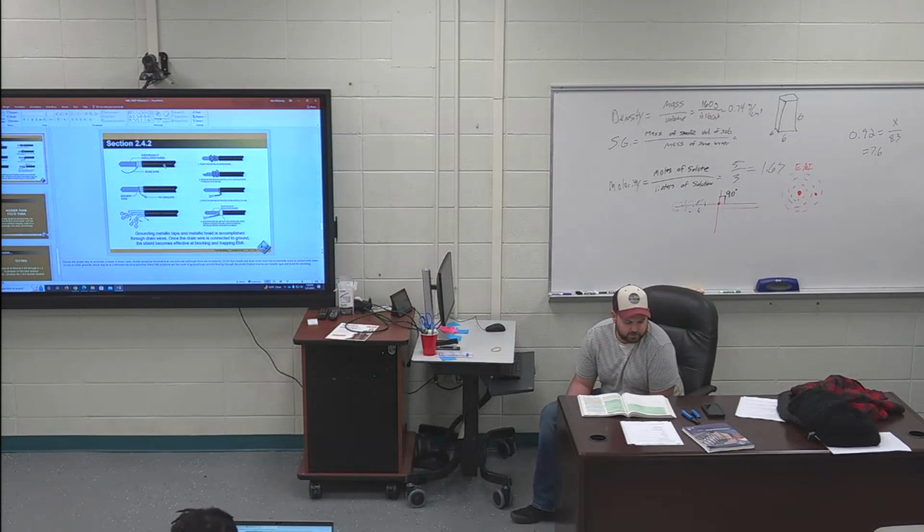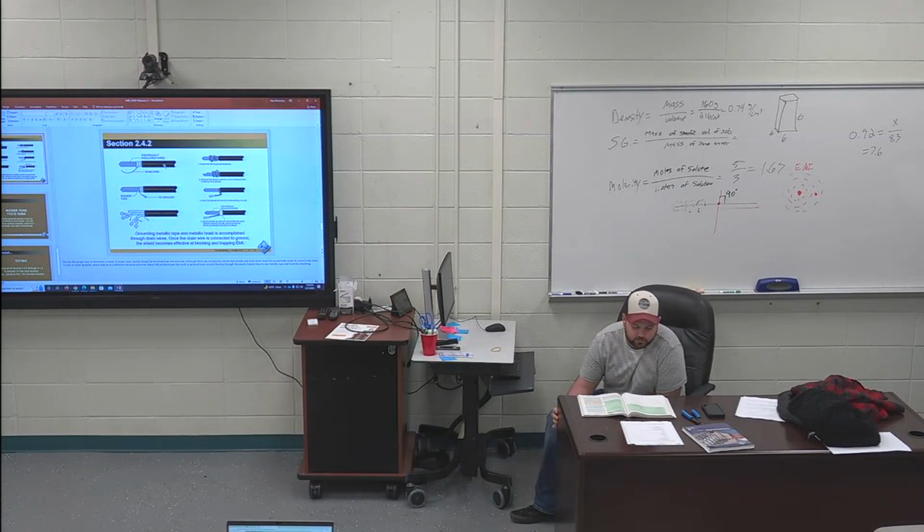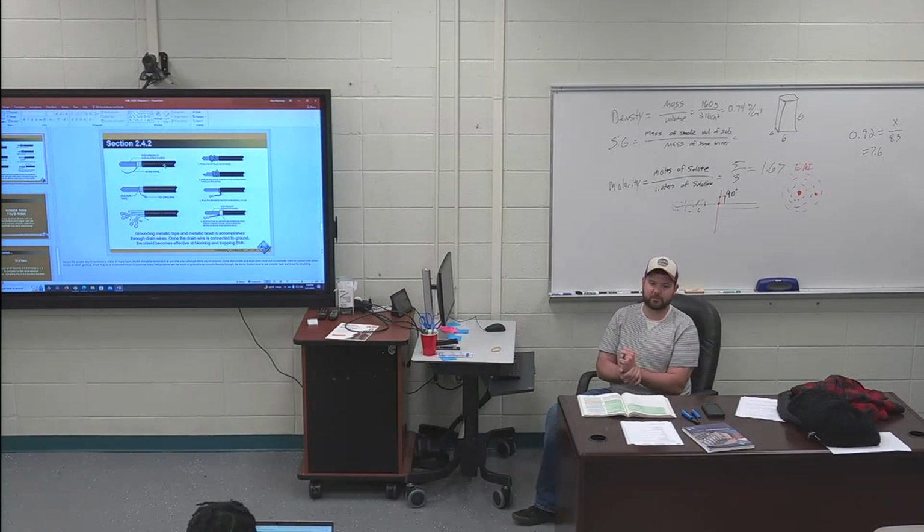Number one, wires installed in spring-loaded terminal blocks are held in place by spring contact, A. Two, coaxial cables are terminated with type F connectors, which is C. Three, a service loop should contain sufficient extra wire to allow for one repair. Four, primary solution for EMI interference in low voltage circuits is adequate physical separation, separating your communication and your power wires.